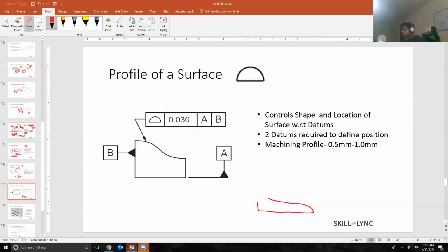tolerances. So for a machining tolerance, again, you can have anything between 0.5 to 1 is perfectly okay. And the supplier should be able to make any part, a machine part between 0.5 to 1. If you go tighter, 0.1, then he will just add cost to it.